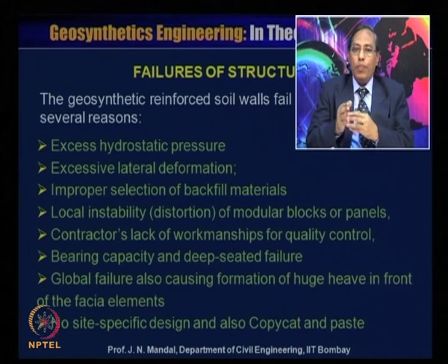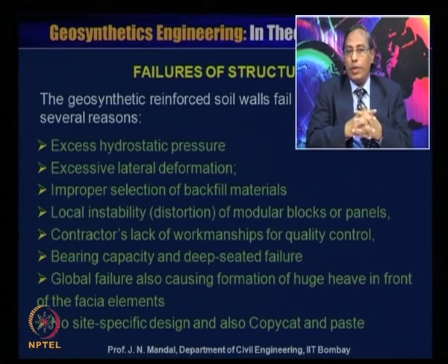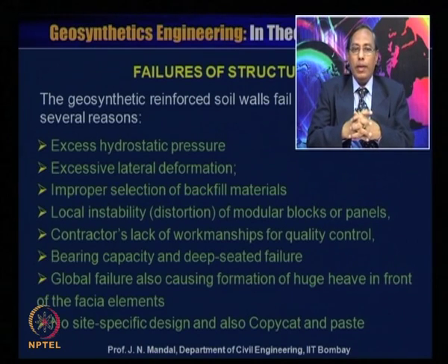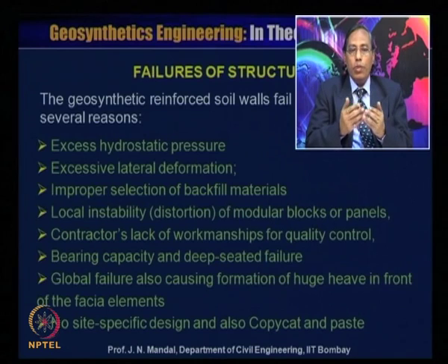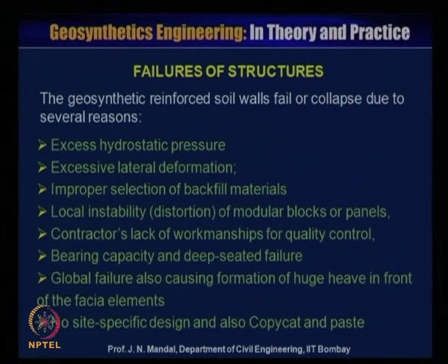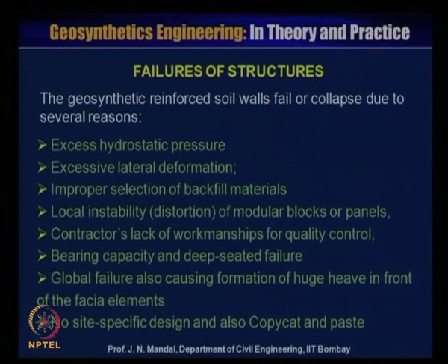Most of the time, whatever locally available material you find, you should not use it. You have to check whether that material is suitable or not, whether that material satisfies the proper gradation or not. I have shown you earlier the different kinds of systems, what will be the percentage passing through that material, whether it is 15%, 0%, you check and follow up. Because most of the structures also fail because of improper selection of the backfill material, this is also very important. And local instability, distortion of the modular block or the panel.